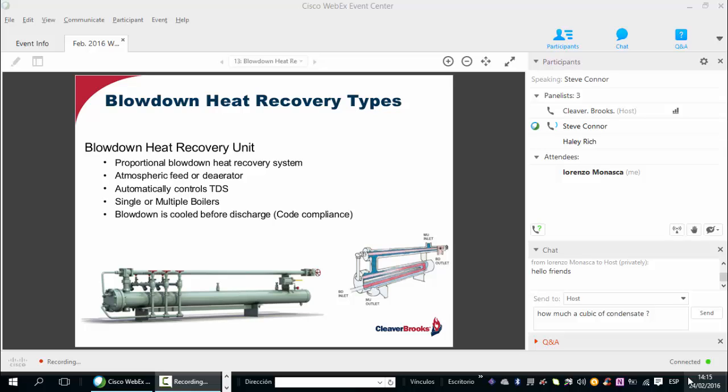And you know, along this line, what never ceases to amaze me, and this has nothing to do with recovering condensate per se, is that when we have situations where there is considerable continuous blowdown coming from the boiler to maintain the proper total dissolved solids, or TDS, level in the boiler, why this effluent coming from the boiler is not passed through a heat exchanger, transferring the heat to the boiler makeup water before going to the feed tank, be it a vented or a pressurized receiver, is just beyond me. Maybe it's just never thought of.